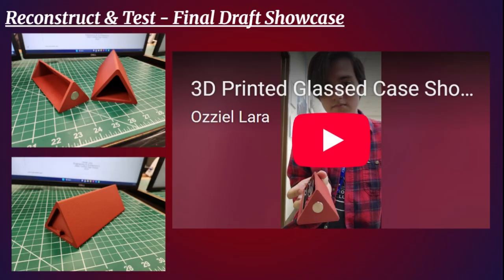Now, before I play my video, let me give you a quick overview of my glasses case design, again to refresh your memory. My 3D printed glasses case design consists of two triangular parts: the actual case itself and the protective shell. The case is supposed to slide into the shell and stay inside thanks to both magnets sticking together due to the magnetic force. With the hook present on the opposite face of the magnet hole, you're able to pull the case out of the shell with ease. The case was filleted in order to remove the possibility of the case stabbing anything such as notebooks or other objects around it.